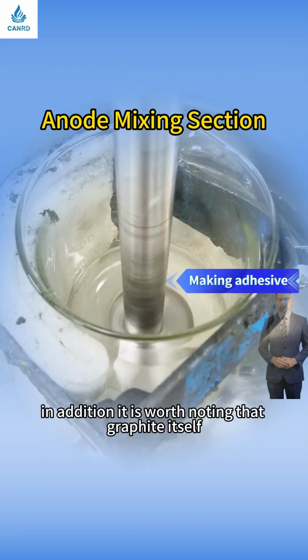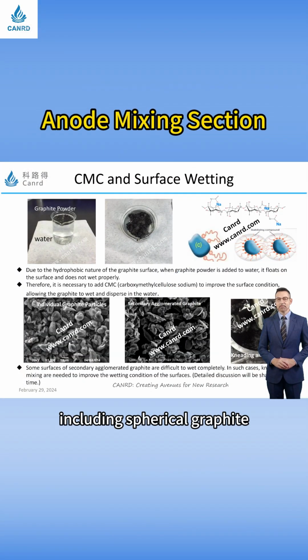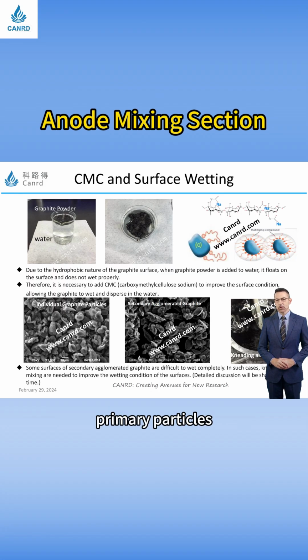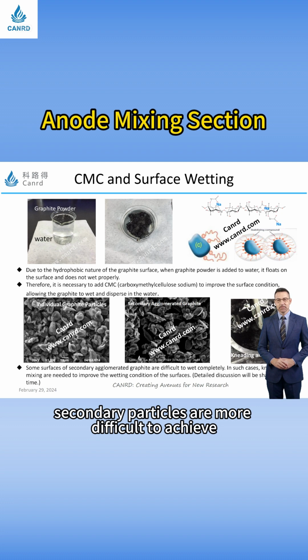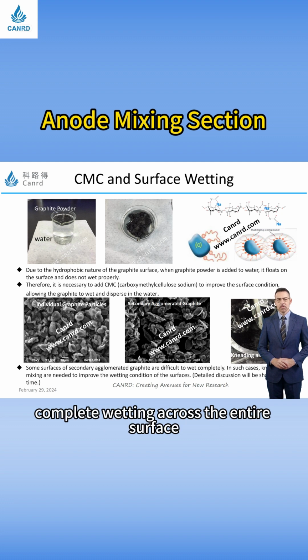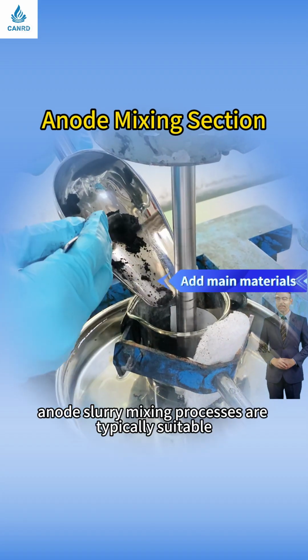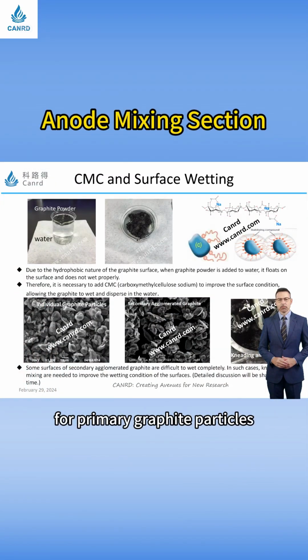In addition, it is worth noting that graphite itself comes in many different forms, including spherical graphite, flake graphite, and secondary agglomerated particles, among others. Primary particles and secondary particles exhibit clear differences. Specifically, secondary particles are more difficult to wet completely across the entire surface. Therefore, conventional anode slurry mixing processes are typically suitable for primary graphite particles.